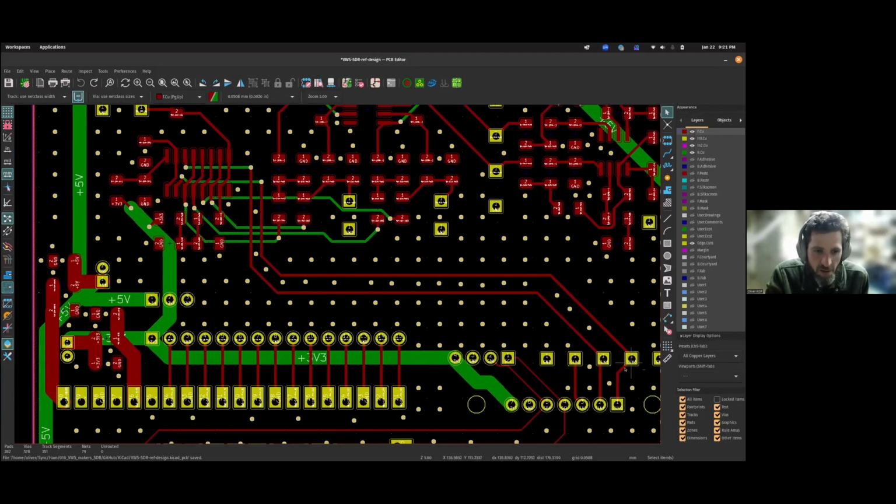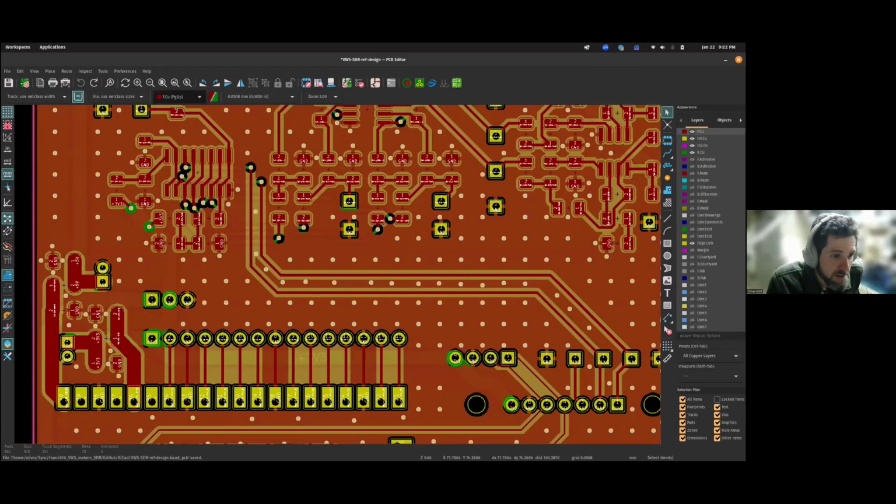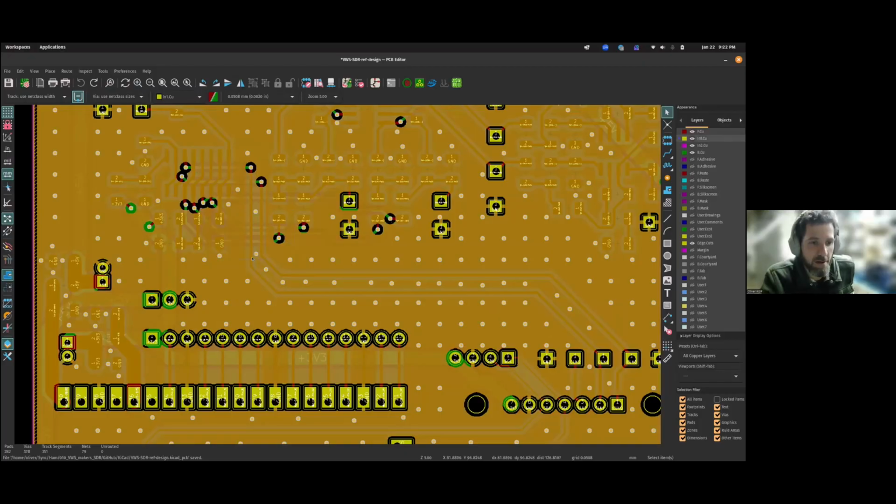And similarly here, these are the SDA and SCL, the I2C lines coming over here, crossing over some RF lines. You wouldn't want to do that on a 2-layer board, have a digital line break the ground plane of an RF line. So what does one of the middle layers look like? If I turn this on here, there's inner copper. There we go. That's what the copper layer underneath the top layer looks like. It's basically solid copper, except for where the vias are and the through-hole components.